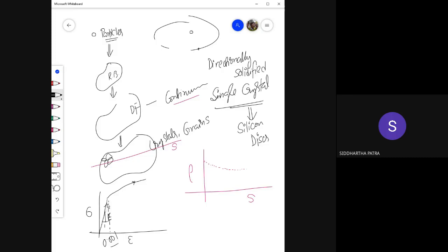So this is the loading curve. We always draw the loading curve. Okay, but what would happen if I unload, let's say from point P over there? Sir, some permanent deformation remains, and the curve goes back to the strain axis, but there is some permanent deformation that is remained.